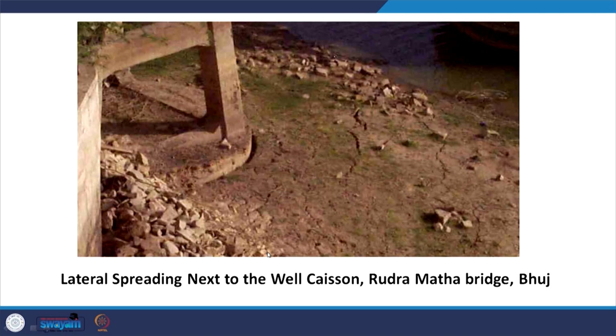And if you see in this slide, there is a well here, and there is lateral spreading occurring here. It is due to liquefaction-induced lateral spreading, because the soil here got liquefied, and as a result there is spreading. This spreading tries to displace this well foundation, but the well foundation was properly designed and it could easily survive.